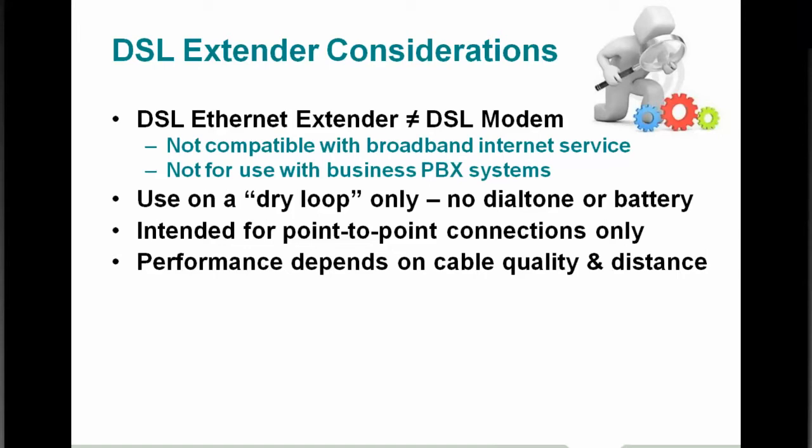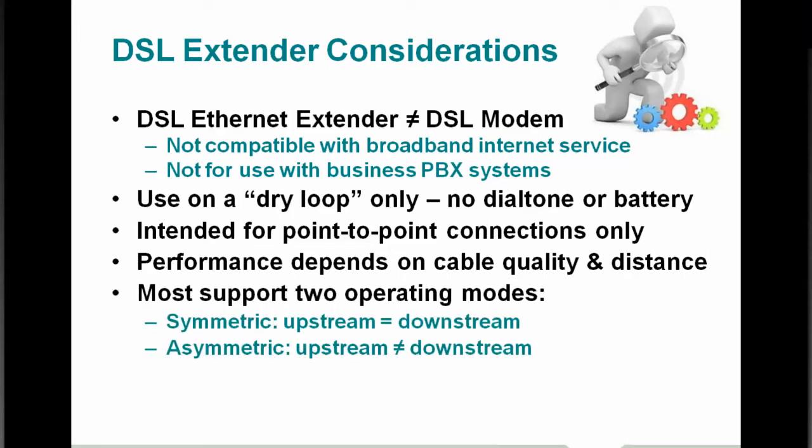Also, just to highlight, we took a look at the two different formats to use: asymmetric versus symmetric. Your performance is going to depend upon the quality of the cable, the distance, and the hardware unit that you choose to utilize for the application, right? So you take that into account when you're designing, specifying, and working on those systems. Also remember that asymmetric versus symmetric depends upon your actual application.